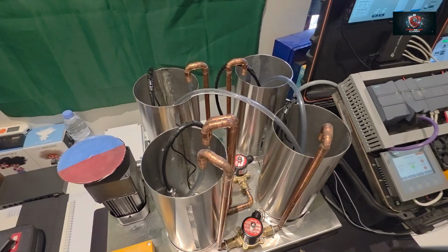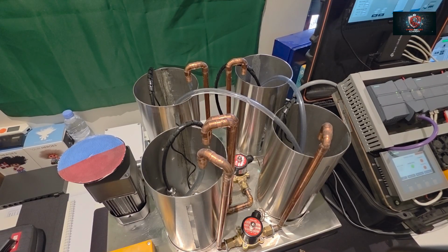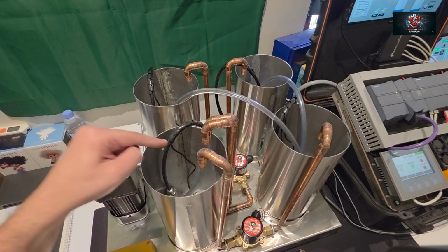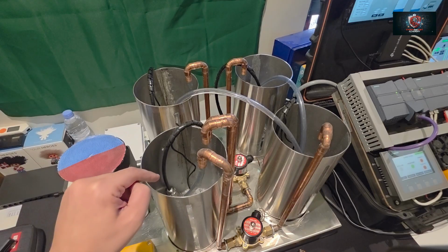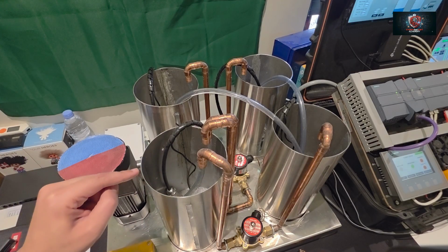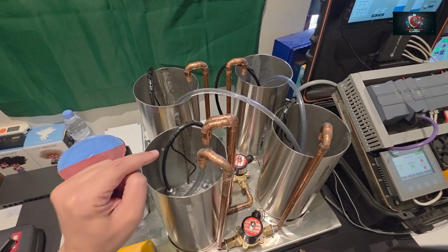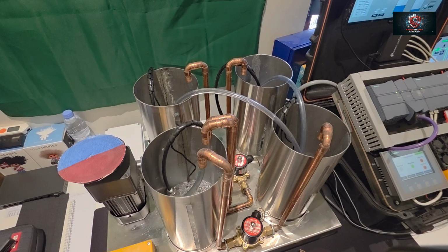We go back here. Okay, let's start the process. I will switch off the emergency mode. You see now the filling process has started, and now we are filling the tank with distilled water. Okay, then at some level, based on the defined value within the PLC, and of course by the operator within the HMI, it will stop at some point. Then the chlorine injection will start filling, then the mixing process will start. Let's take a look at it.